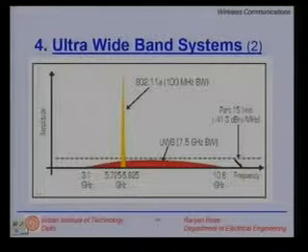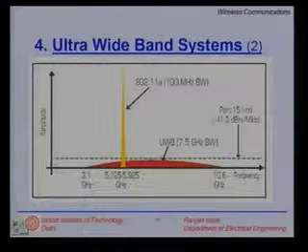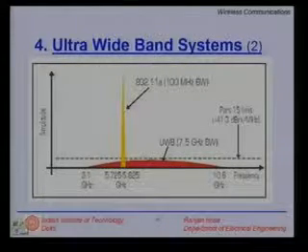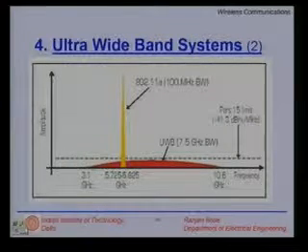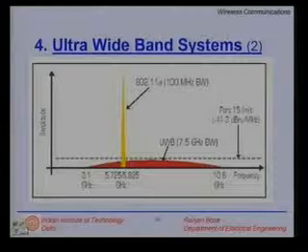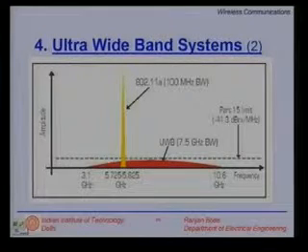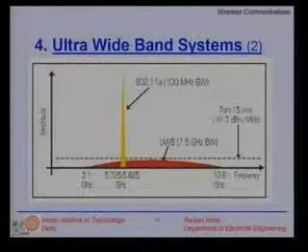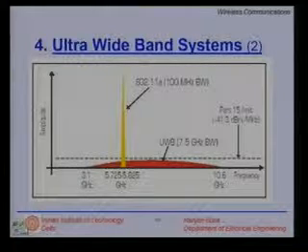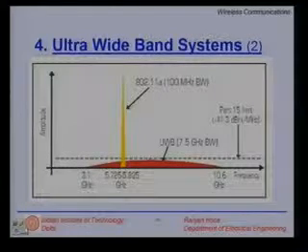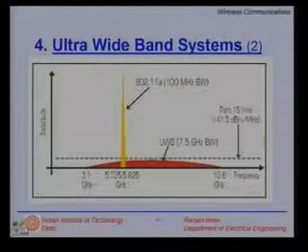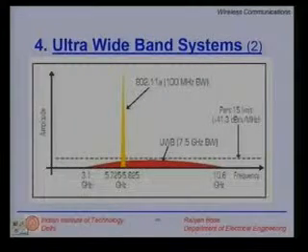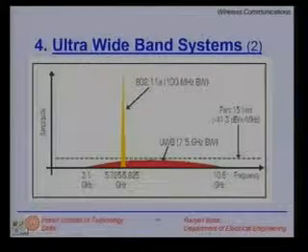A lot of appliances which work at around 2.4 gigahertz typically radiate unnecessary power below this dotted line. So anything below the dotted line is an acceptable out of band emission limit. UWB interestingly has been designed to emit below that level. What does it mean? It means I don't need any license.